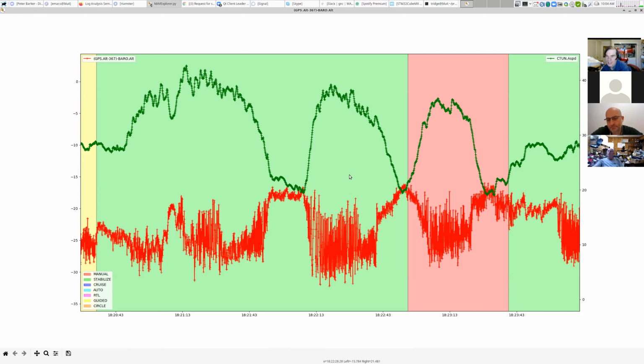Exactly. Yes. So this one, he probably needs a little piece of sticky tape to solve this problem, and he would then find that his baro reading would be a lot more consistent. Now, of course, you may be able to stop that noise. We don't know the setup. It could be that he needs to block holes on the fuselage, or could indeed open up other holes to equalize pressure or do something. We don't know. Yep. So that's our likely cause.